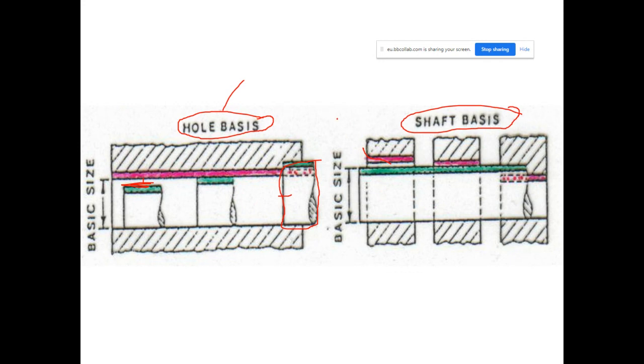Because in industry we have standard cutting tools in size. Say that you need to have the mating in a certain specific order. So for having the mating in that order, say that the diameter of the drill is to be, for instance, 12.5, let's say 5.3. Okay, well, go to the market and try to find a drill cutter, a cutting tool.